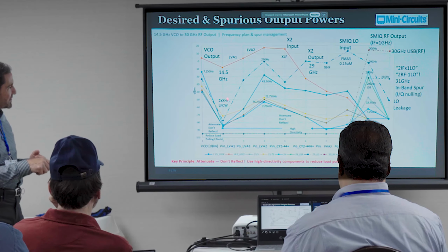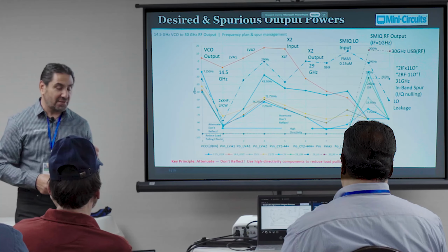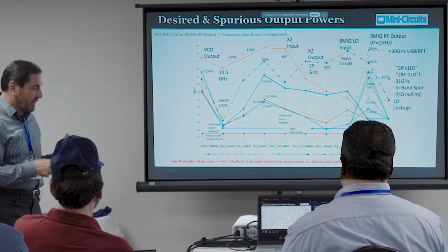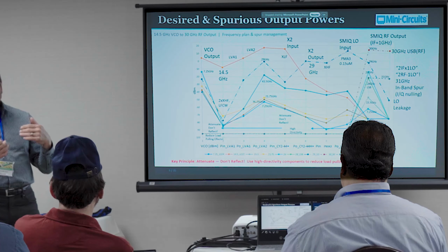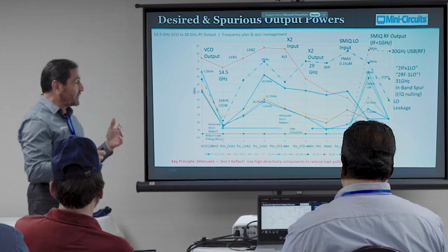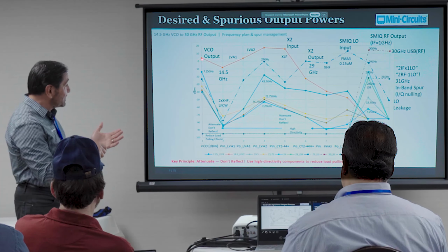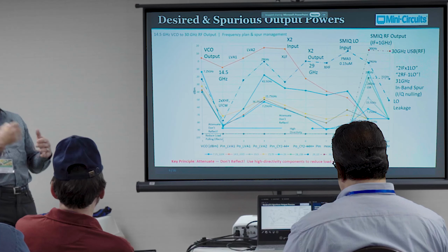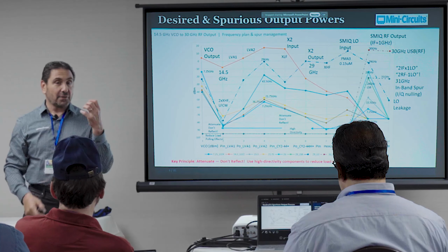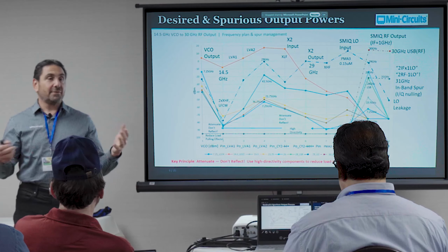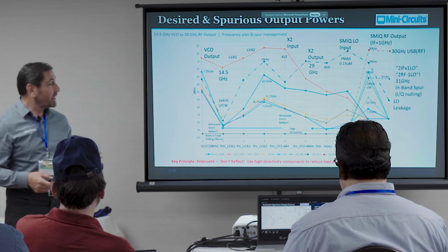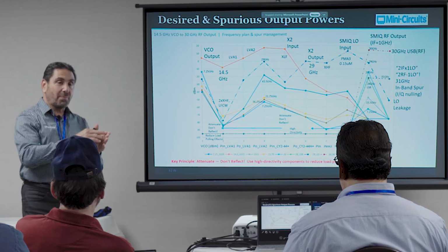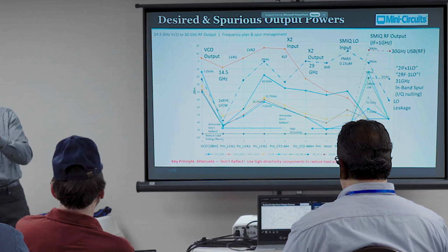So we go through a series of what we call XHF. These are the reflectionless high-pass filters. Again, they don't reflect, they attenuate. And that's very good, because some of these signals are fairly high level. You don't want them reflecting back into the VCO. You'd like to attenuate them. People sometimes use large attenuator pads, but you're taking a hit in loss there. The reflectionless filters allow you to have a pass band that's low loss and a reject band that looks like a high loss attenuator pad.